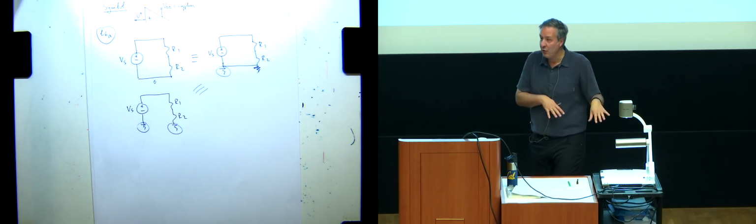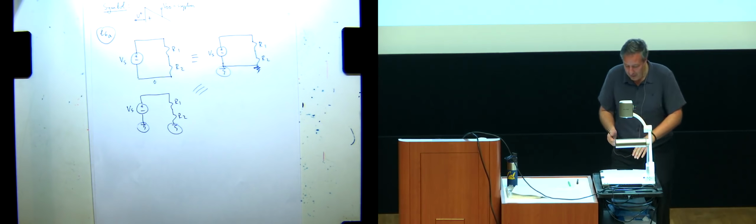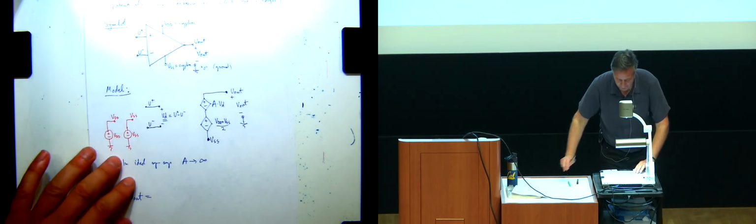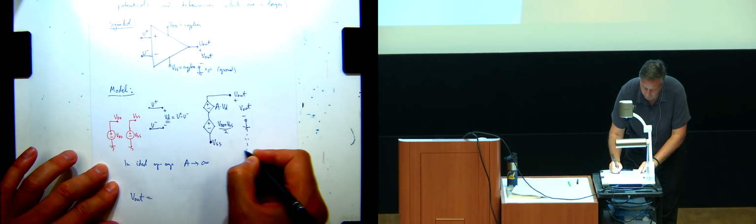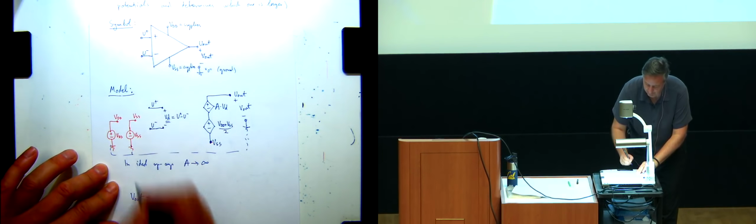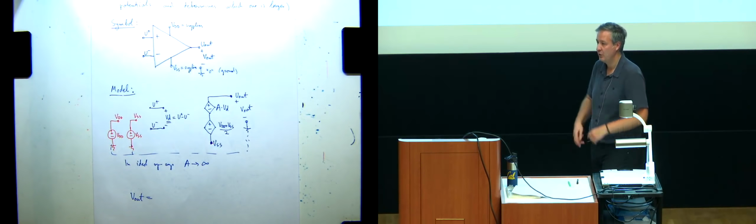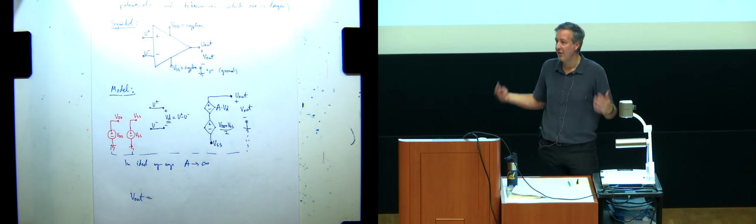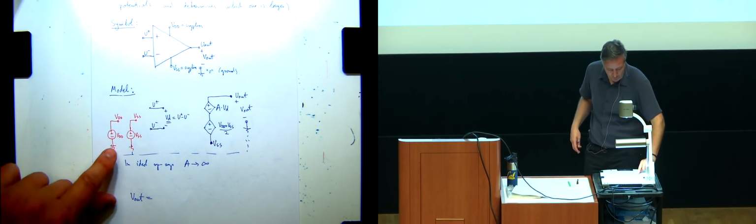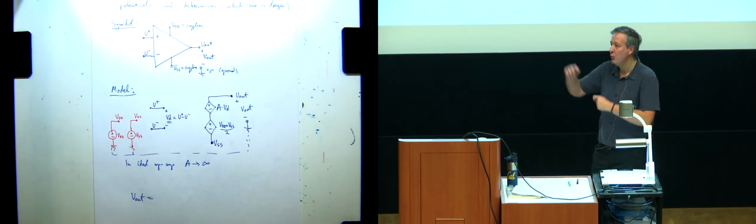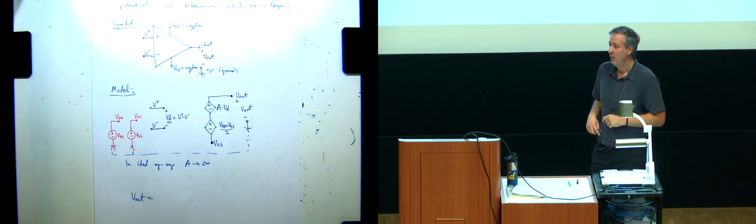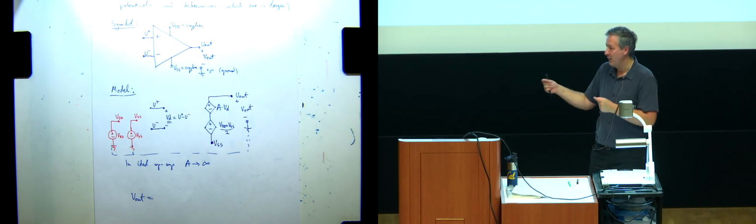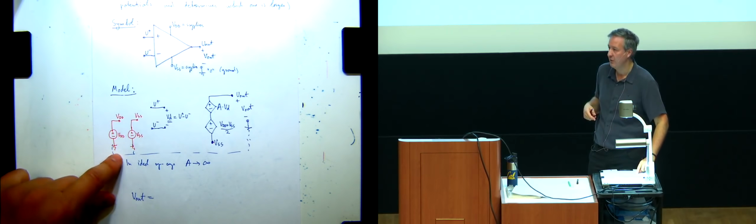But the way I'm going to draw schematics, I really don't want to draw wires all the way between all of these. It's going to be very messy. When you start drawing bigger schematics, it's just going to be very messy. So we're just going to draw these little squigglies and assume these are all connected. When you're doing your board layout, you've got to be very pedantic about connecting all these to some common potential, right? This reference node. Does that make sense?